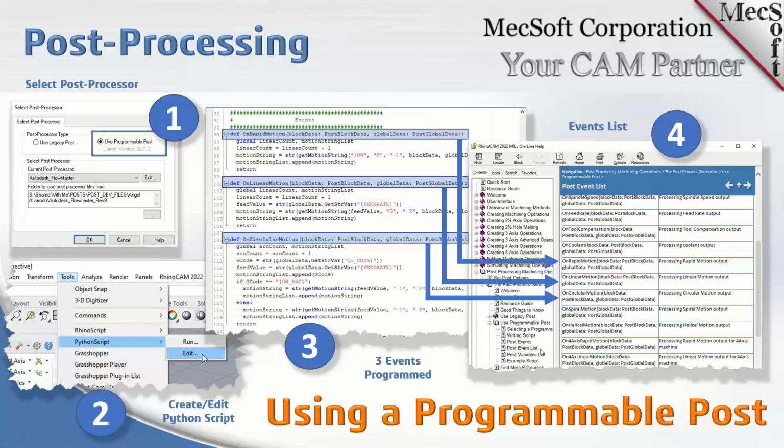This Python programming system is an event-driven architecture, if you will. It's been designed as an event-driven architecture. What that means is when the system is cycling through the internal toolpath, every time it hits a certain interesting item, for instance a tool change, which is a very interesting thing that you want to handle, that will be treated as an event.